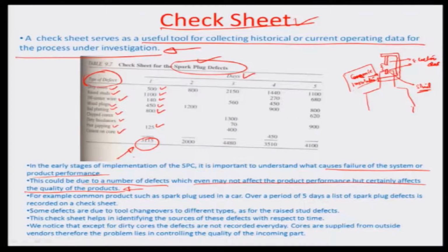So basically now you are clubbing together the defects of certain types, and these are, mind you, the defects which are the most concerning ones from the fitment point of view, and that is how a whole check sheet is designed. Okay, so the purpose of the check sheet is really to record statistically what is the frequency of occurrence of a certain particular defect in a tabular manner, which you were earlier doing in the histogram manner, in probably a graphical way or in a bar chart representation.